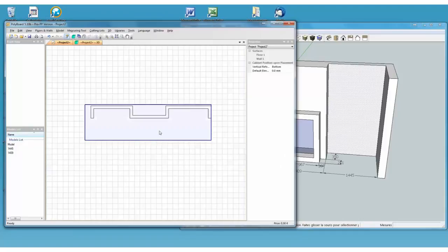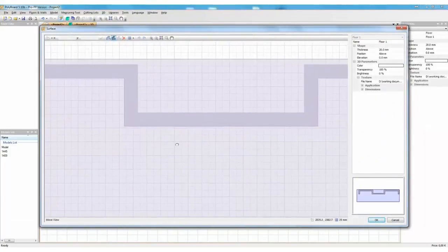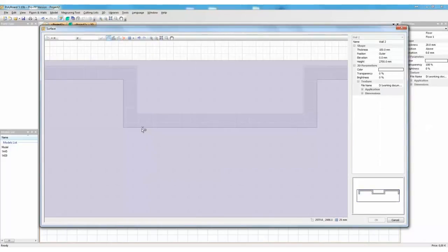How do I do that? Well, I see that the fireplace sticks out approximately by about 200 mil, and let's go straight into the project mode here and set up a fireplace. Well, how do I set up a fireplace here? I'm going to just draw a wall. I'm going to click it using the grid snap approximately here, and approximately here.